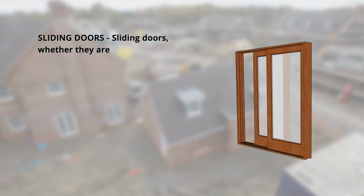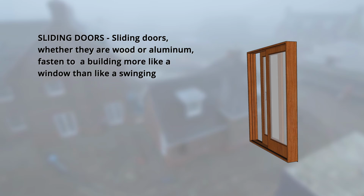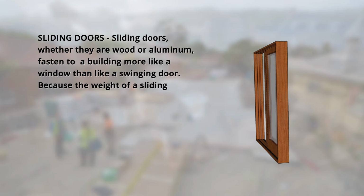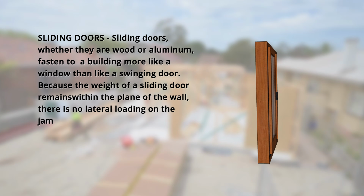Doors. Sliding doors. Sliding doors, whether they are wood or aluminum, fasten to the building more like a window than like a swinging door. Because the weight of the sliding door remains within the plane of the wall, there is no lateral loading on the jamb of the door unit.